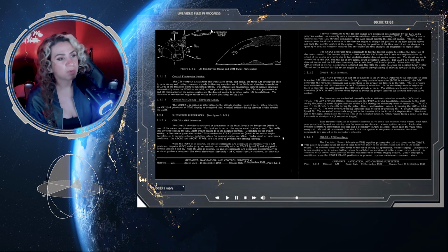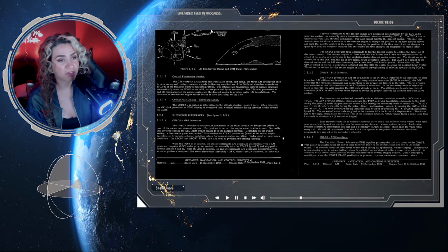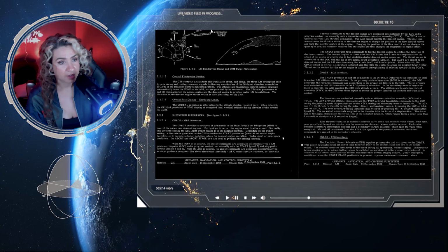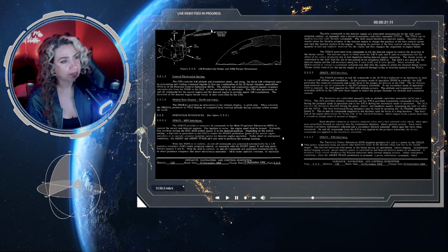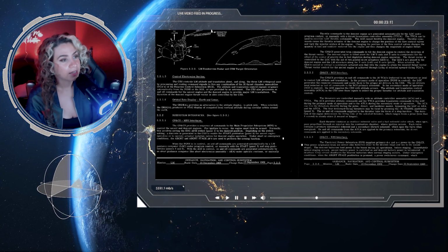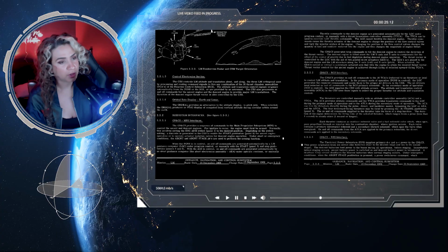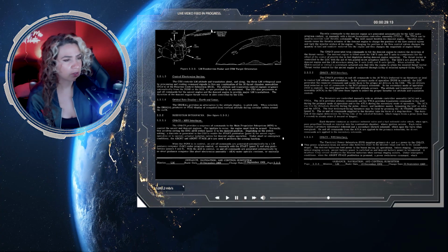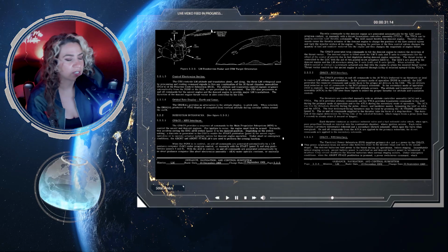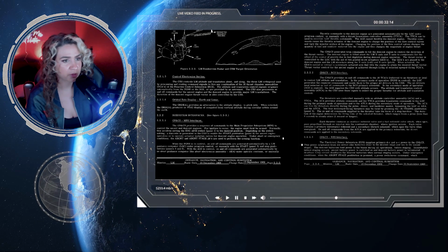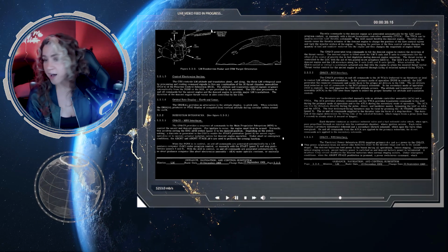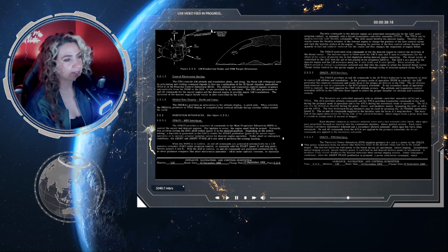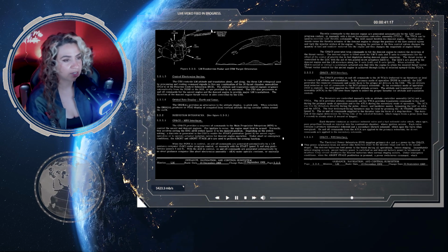The 4 downward firing thrusters may be fired by pressing the positive X translation button, panel 5. The on and off commands supplied to the thruster take the form of a step function. The duration of the signal determines the firing time of the selected thrusters, which ranges from the pulse, less than 1 second, to steady state, 1 second or longer.